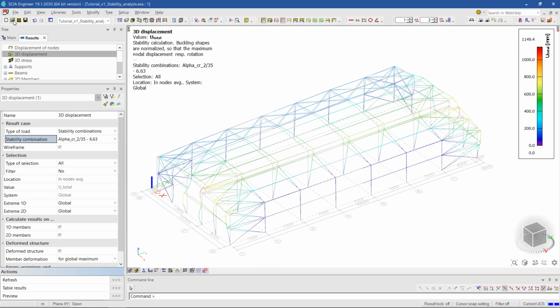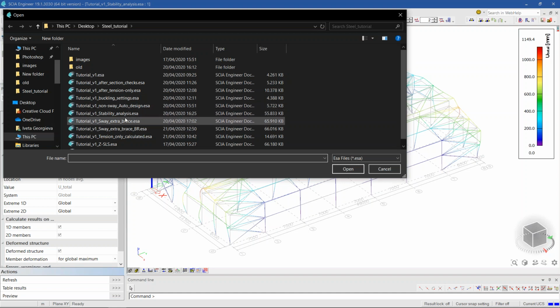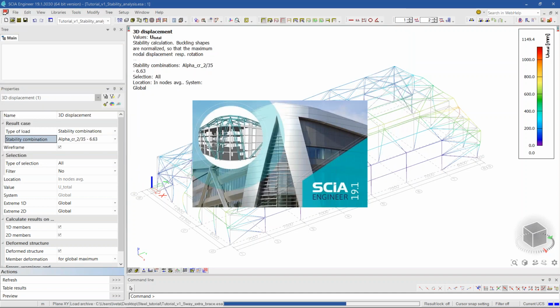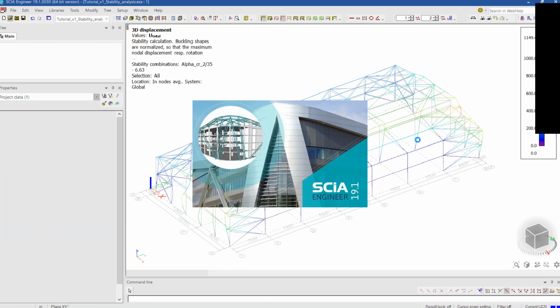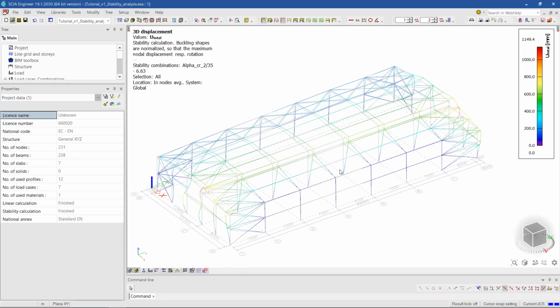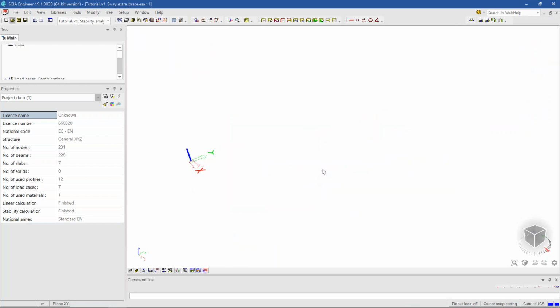And so the first reflex I had to solve this is to add some bracing here where the displacements are large. I think that if I would add a brace here in this field, this deformation will be killed once and for all.